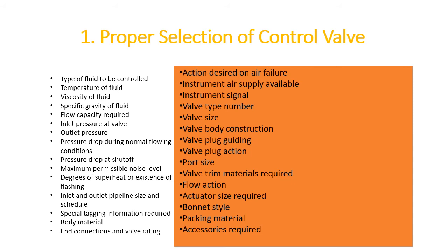Another thing, for the selection of the control valve, the process inputs have to be accurate. There have been situations where the actual process condition is not reflected in the process datasheet. So the maximum or minimum condition that is mentioned in the process description is way far from the actual condition. In that case, even if you are an instrument engineer or valve design engineer and you have done your job, due to the change in the process condition, your selection may go wrong.